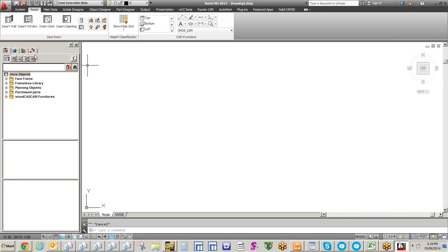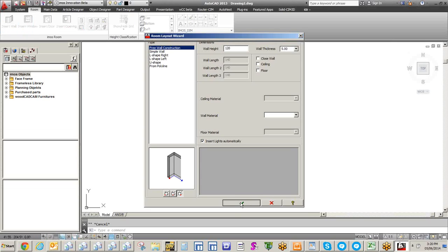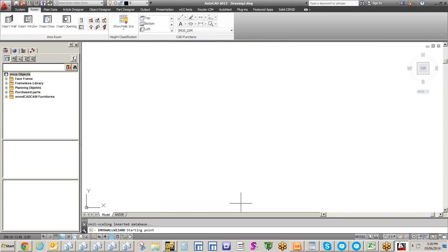All right, in this demonstration, we'll begin with the thought of working on some architectural submittals. Just real briefly, we'll tell it that we want to insert some walls and give particular walls some dimensions. So here in AutoCAD, I can select any position that I'd want to get started, and then type any dimensions. For example, 120 for the first wall, and we'll put 144 for the second. I'll hit enter a second time whenever I'm done placing walls.